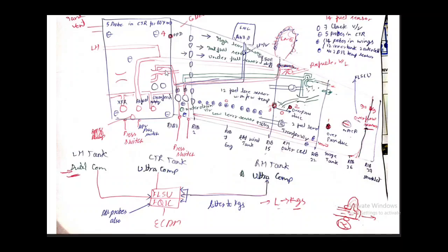We'll discuss in another video how the transfer valve works with the Venturi. Here I am just drawing the Venturi system, showing how the fuel gets transferred. If you see, fuel is going to the inner area. And in the left wing and right wing the concept is the same, so I am just taking the example of the right wing.